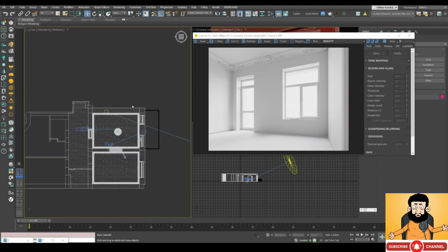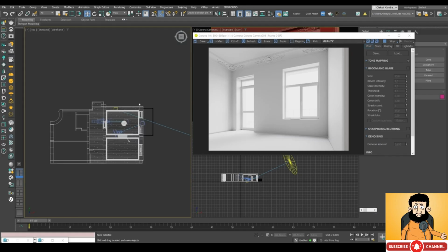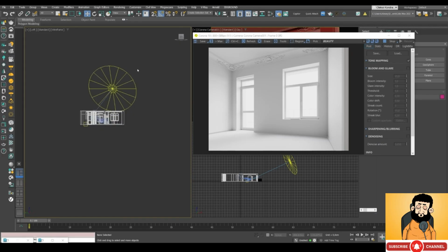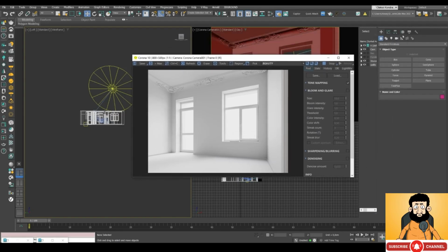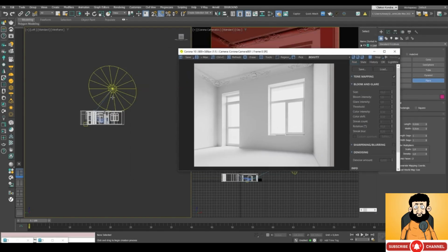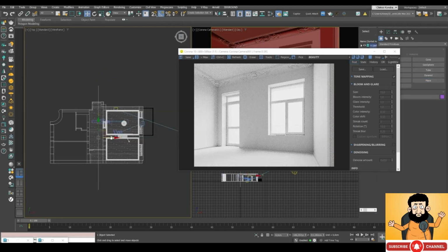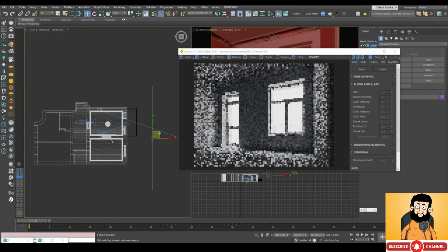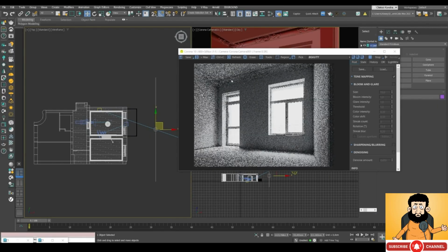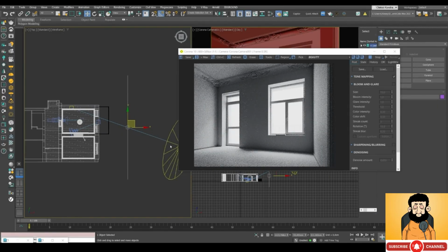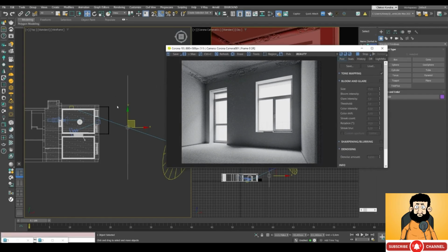All right? Now here's another important thing. The background must always be perpendicular to the camera. So let's create a plane, and it's going to be a standard plane. We'll put it outside the window. Now pay attention to how the light changed instantly. Well, that's because we have the sun in our scene, and the plane is blocking out the sunlight. So we need to exclude the plane from the light.